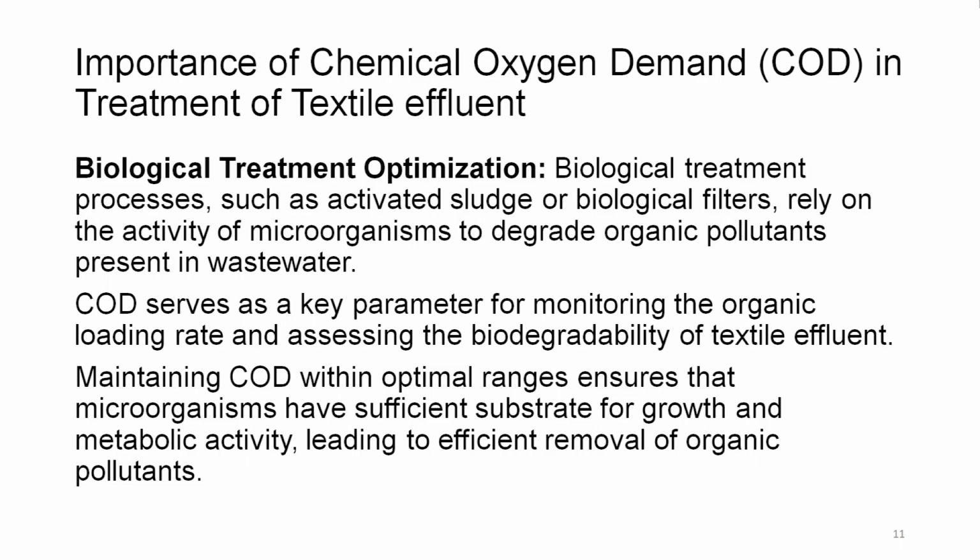Biological treatment optimization. Biological treatment processes such as activated sludge or biological filters rely on the activity of microorganisms to degrade organic pollutants that are present in the wastewater. COD serves as a key parameter for monitoring the organic loading rate and assessing the biodegradability of the textile effluent.